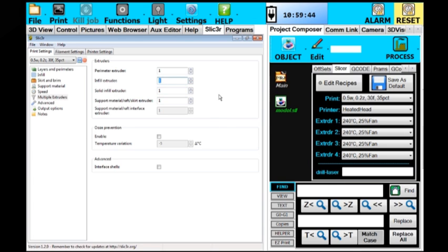Another benefit from this is that we're not going to ever specify in our G-code which head to use. So you can run the same G-code with your head loaded in slot 1 or 2 or 3 or 4, and it's going to print it with the head that it finds. The last head that it locates is the head it's going to use, unless in your G-code you specify a particular head. Then you have to configure your machine to match your G-code, or edit your G-code to match your configuration.